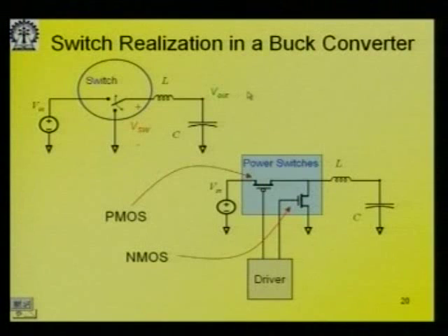We will not go into the details of that, towards the end we will summarize some of the possible converter configurations, but we will look at how we can realize a buck converter in a VLSI circuit. So, this is a switch. Now, ideally speaking, if you have one switch here, that should be enough. What we can do is that whenever we are putting this back onto this, we can put a diode so that through that this circuit can be completed. It used to be called a freewheeling diode.